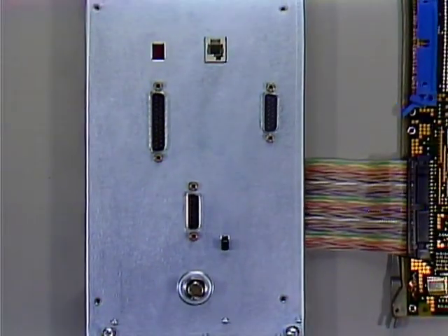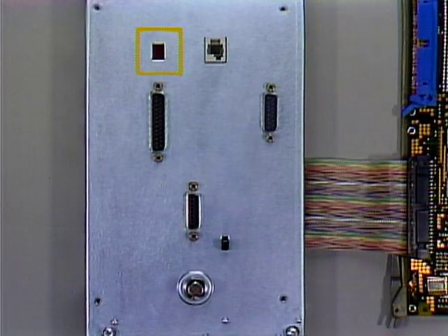The cover assembly contains a 15-pin connector for the keyboard and mouse or tablet serial lines. This connector supplies plus 5 volt, plus 12 volt, and minus 10 volt DC power, as well as data and control lines for the keyboard and mouse or tablet. A printer or console serial line on a 6-pin connector. The cover module uses a single hexadecimal digit display with a decimal point for the status output display. Refer to the VAXstation 3520-3540 maintenance guide for the status code definitions.